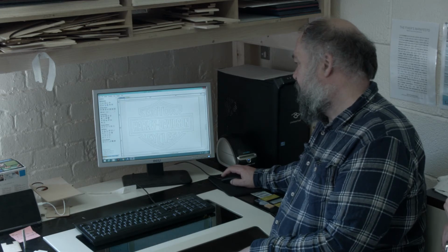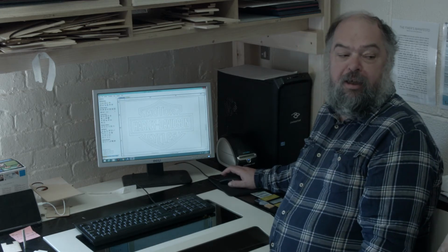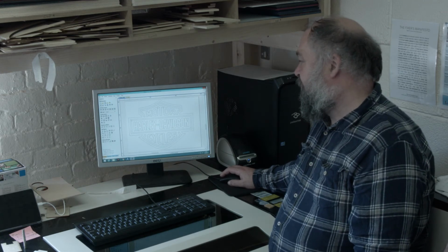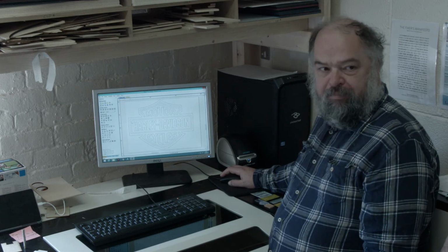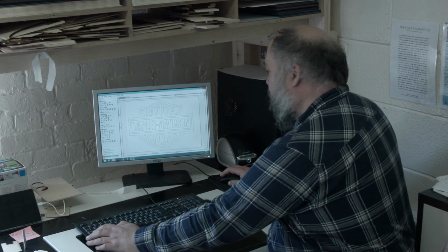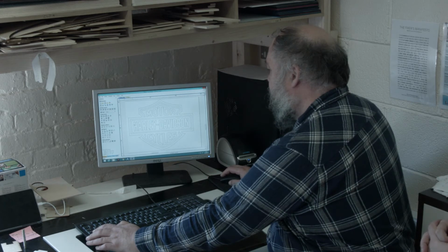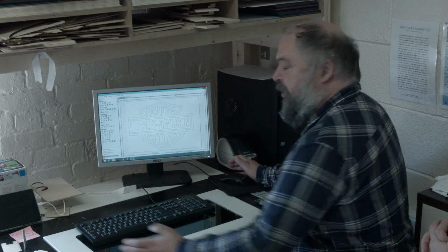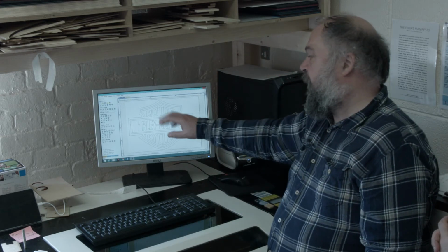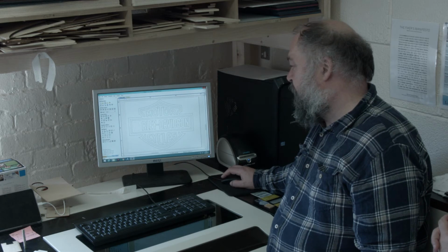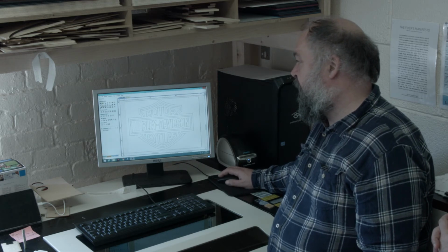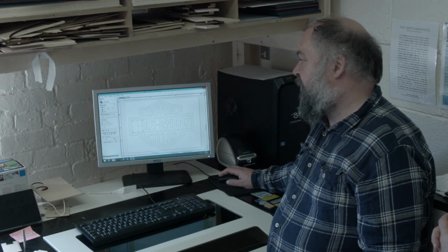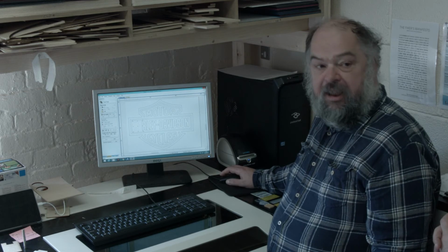And then finally, we have the Harley logo. Yes. So what you can do with that is you can actually select all the profiles that you want. If you're going to have all of these set to a set height, you can go select each of the ones and then set it to a height using the modelling tab under here. You can set how high you want it to be, etc.